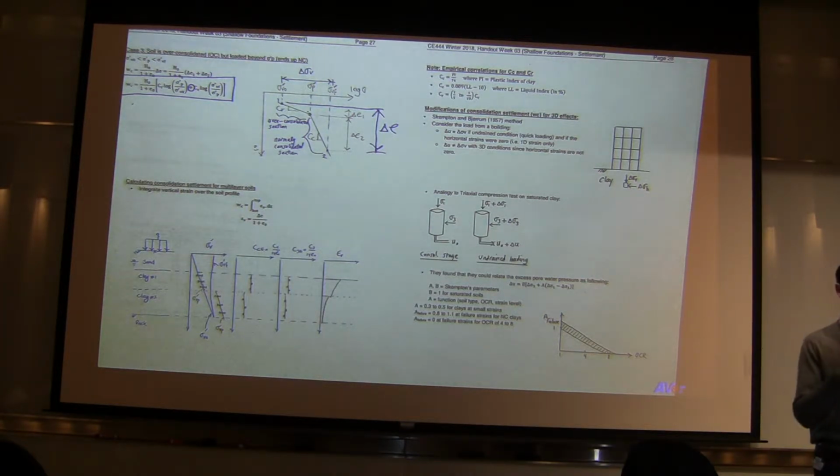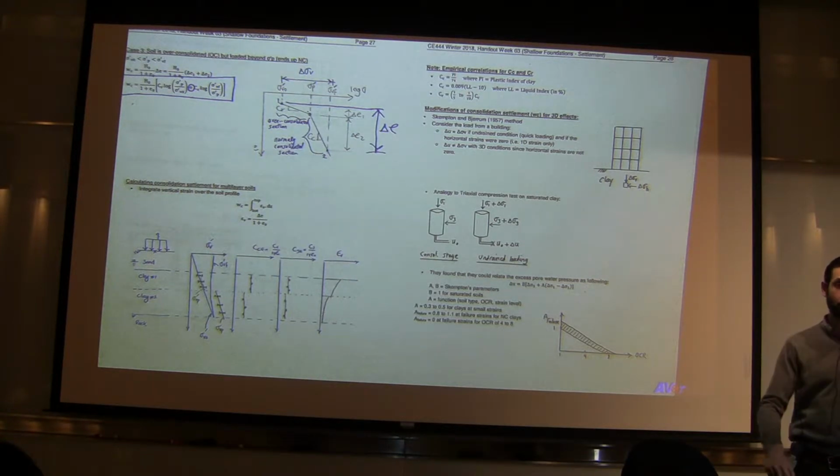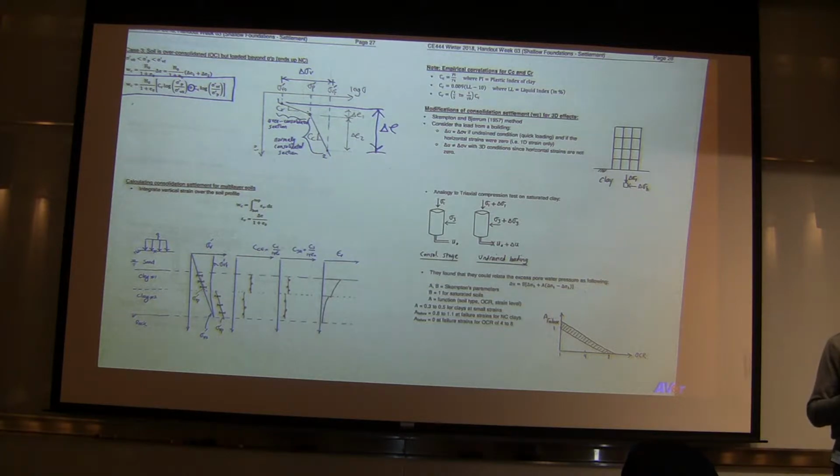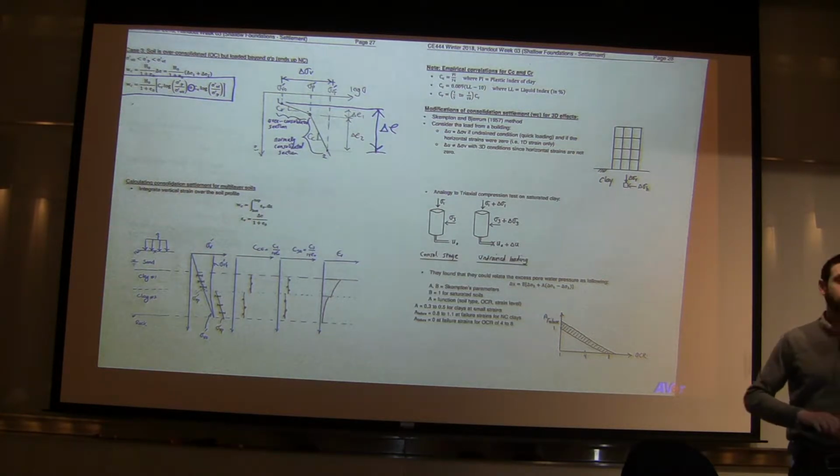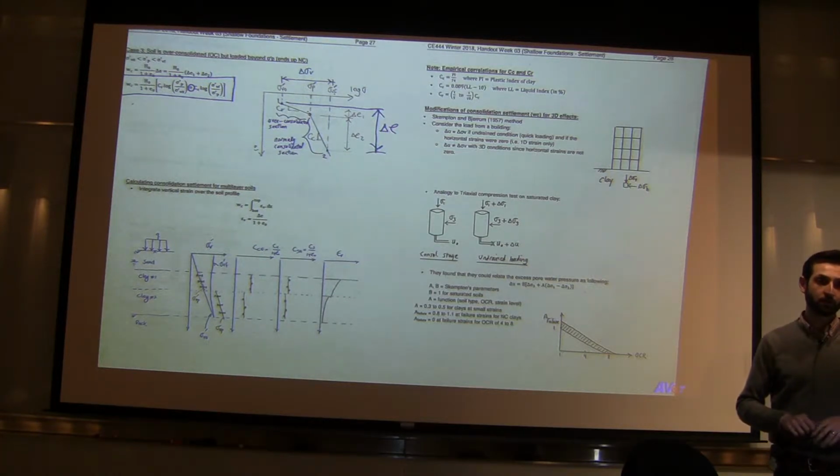Yeah. So I'll tell you what they depend on, and I'll give you a range. For CPT, it depends how deep they go and how many they do at the job site. Basically, they usually charge per hour because they can do one hole and go 100 feet deep, or they can do a bunch of holes, and their costs usually take into account their mobilization costs. Once their equipment is at the job site, they drill as many as they can. Usually, they charge between $2,000 to $5,000 a day.